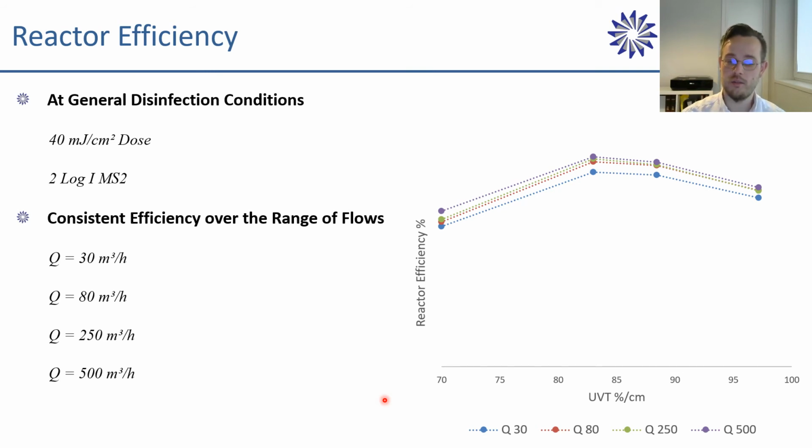And we have chosen the peak to be here because it's a drinking water application. So we are looking at more of a higher UVTs, and it's really easy to deliver the dose at UVTs that are 95% or higher. It is a bit more challenging to deliver the dose in that range. That's why we want our reactor to be optimized for the most difficult condition that it's going to be regularly seeing, which then produces a flat characteristic of that reactor.